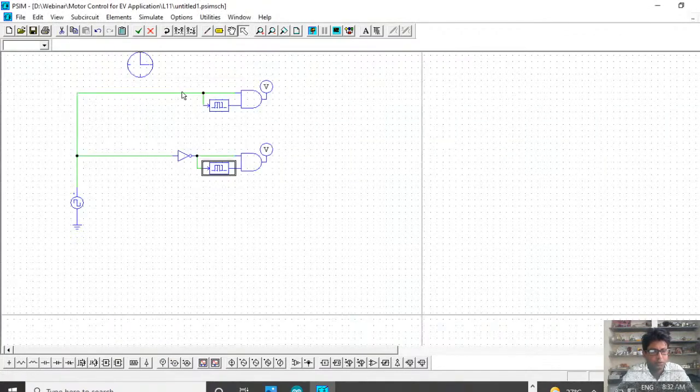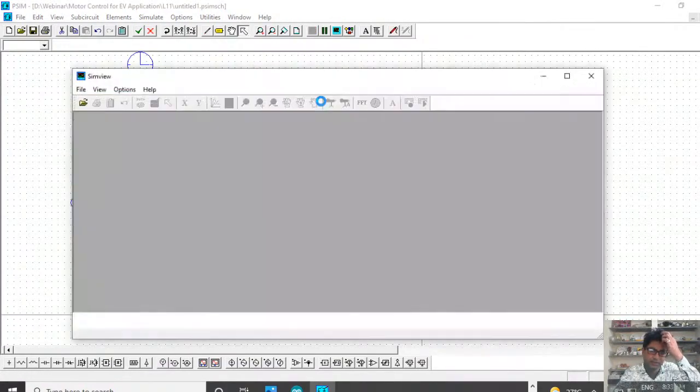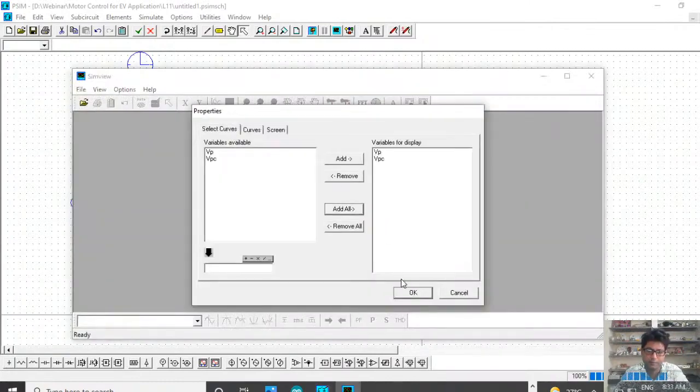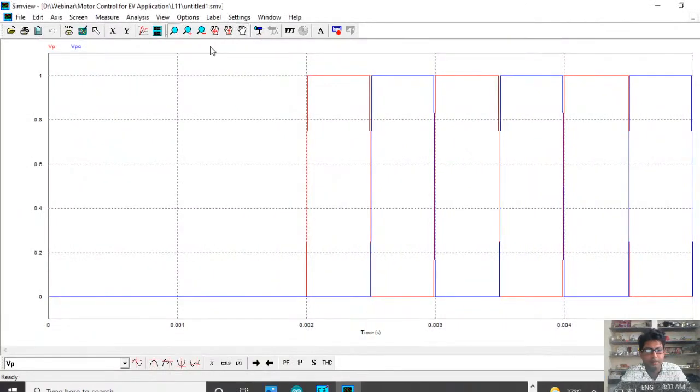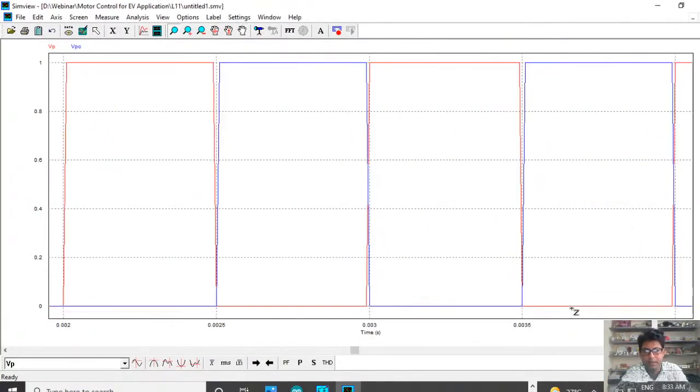So what I am doing is taking the actual pulse and the delayed pulse and doing AND. Similarly, you use a NOT gate, take the same pulse, give it directly to an AND gate, and also give the delayed one. Now let us see how it is. Now you see both the pulses; if I make one pulse area bigger, you see what is happening.